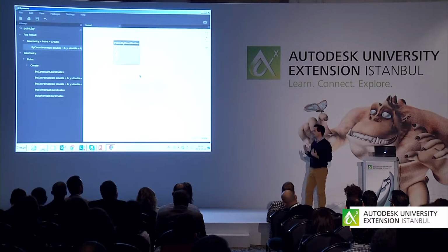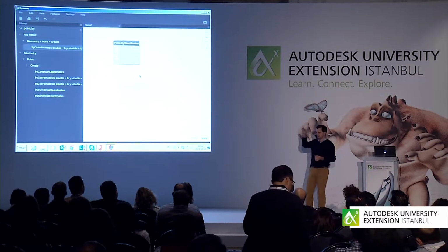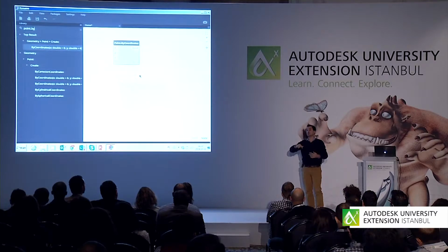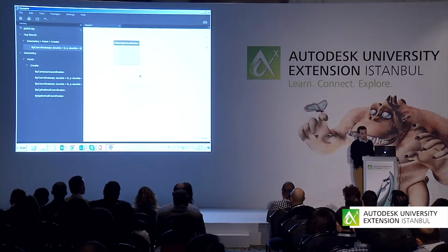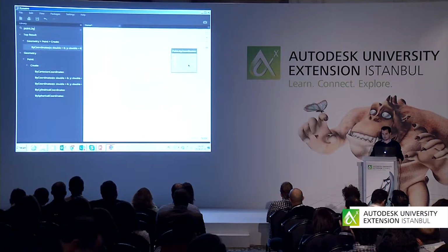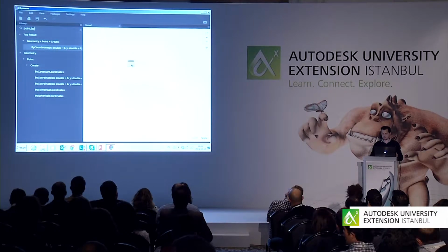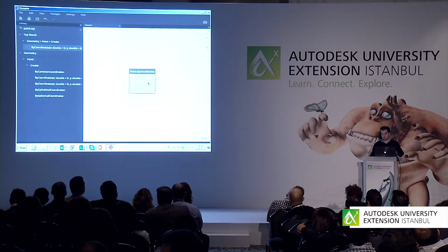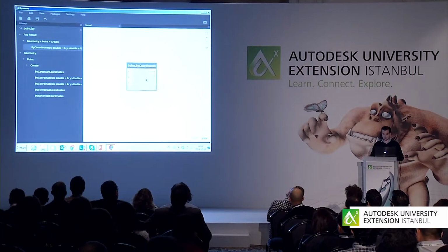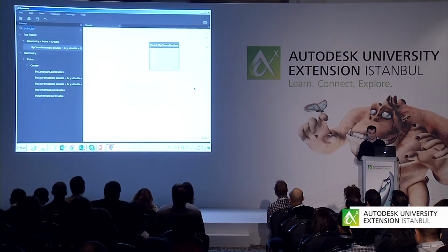But it's very well explained in the videos that you'll find in the learn section. Okay, why Point.ByCoordinates and so on. So if I just drop it on my canvas, as you can see, if I take my mouse and scroll out and zoom in, I can zoom in to my Point.ByCoordinates, and as you can see, I just dropped this icon, but nothing happened, okay?